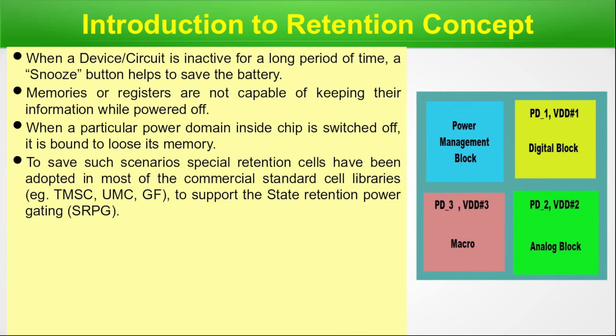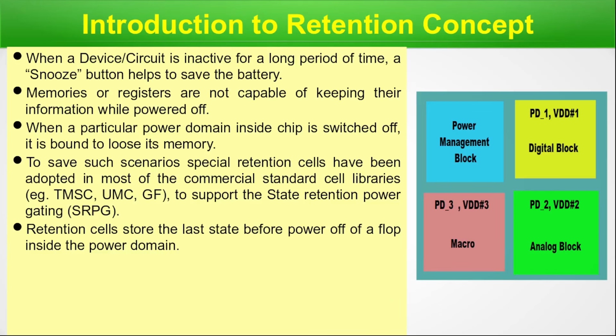To handle such scenarios, special retention cells have been adopted in most of the commercial standard cell libraries coming from foundries like TSMC, UMC, GF, etc., to support state retention power gating, also abbreviated SRPG. Retention cells store the last state before power off of a block inside the power domain. From the right hand side picture, it is clear that if we switch off one particular power domain, the last states will be saved in the retention cells.